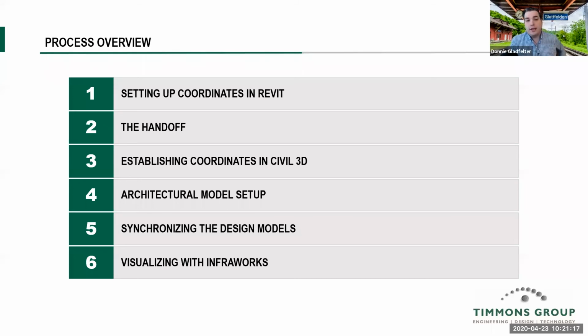Good question. This is the fragmentation of AutoCAD. It really spotlights that a little bit. AutoCAD has a number of different flavors associated to it. And unfortunately, the simple answer to the question is the shared reference point extension is exclusively available to Civil 3D. So you will need Civil 3D for that. Even though Map 3D understands coordinate systems and all of that, it doesn't have that extension.